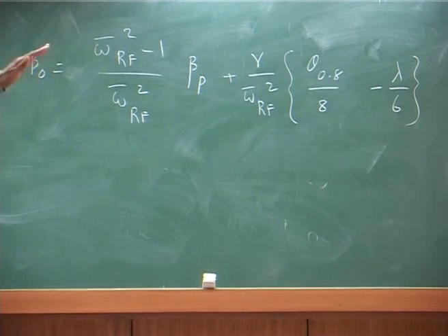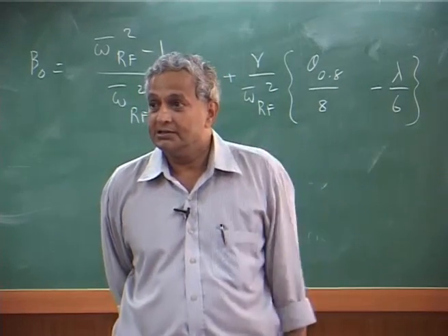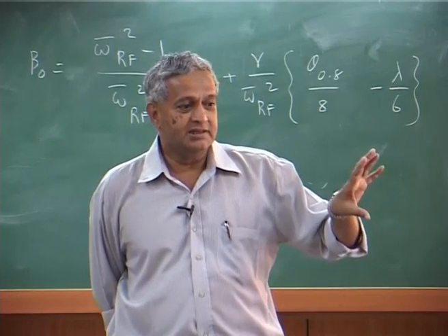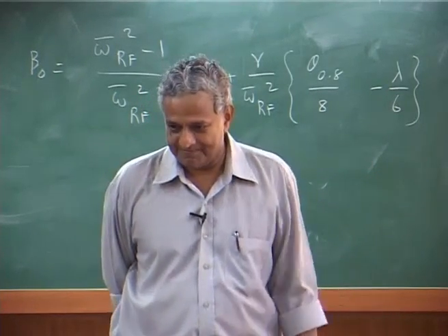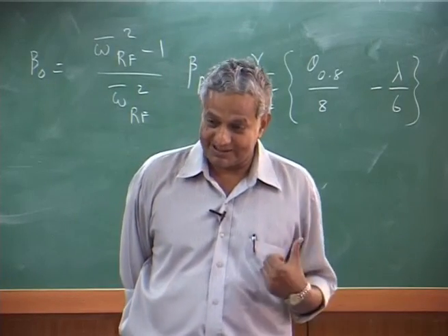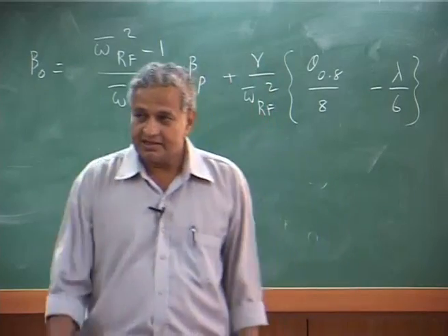Because I said that initially the blade I attach at that location. What angle would I prefer? If you put it at that angle, the blade will not experience any moment at the root, even though I have a spring, but that is set for only one particular flight condition. This is called ideal precone.